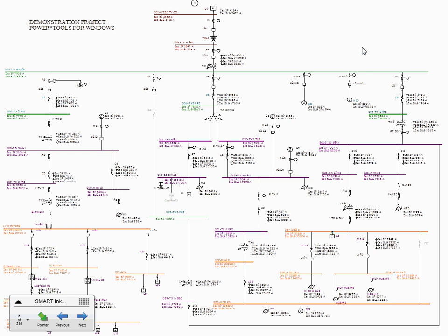These are the buses, and from the bus you have relays. The top is medium voltage. You have relays that control multiple motors, and here's also 4160. You show all the relays and the overcurrent protection device, which in this case is relays, and you go all the way down to what you guys deal with, which is circuit breakers and low voltage. So it shows a lot of information.